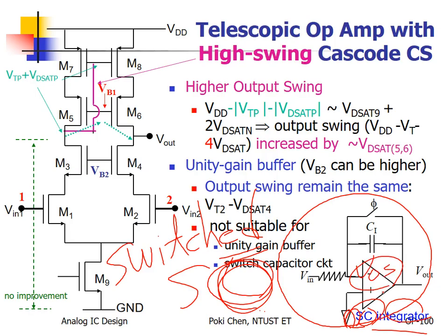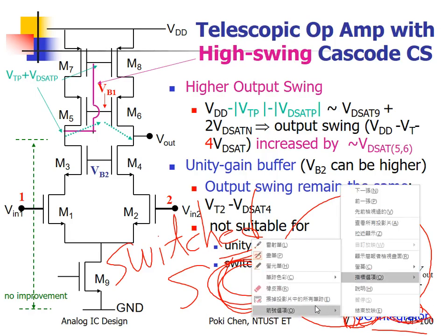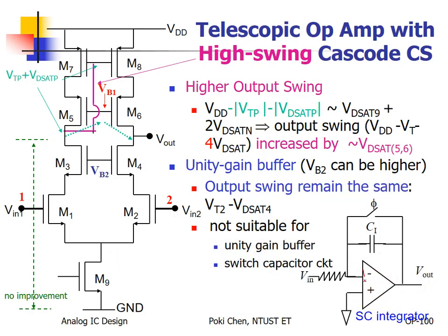Nothing is perfect. Every amplifier has such kind of input offset voltage. But what is the consequence of VOS on integration? Since VOS is a DC term, after fabrication, it is DC, right? So it will cause a DC current flow. I don't care about the direction because VOS is positive or negative, both with 50%.